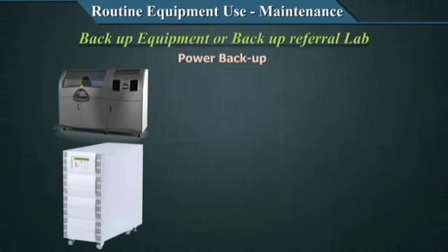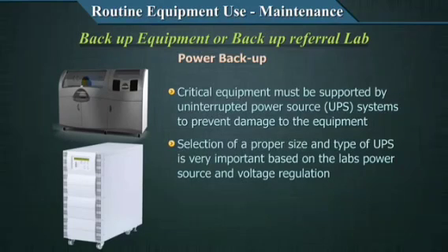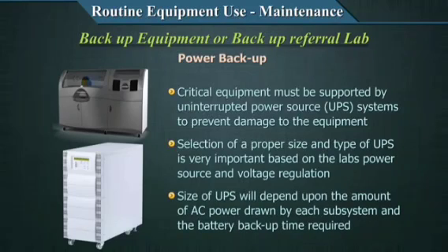backup. All of us in India are frequently confronted with power outages. So critical equipment must be supported with uninterrupted power supply, or what we call UPS systems, to prevent damage to the equipment and to ensure continuity of the services. Selection of a proper size and type of UPS is very important based on the lab's power source and voltage regulation. Size of UPS will depend upon the amount of power drawn by each subsystem and the battery backup time